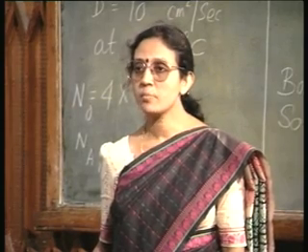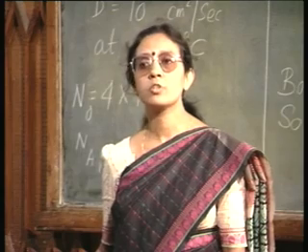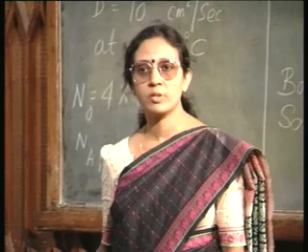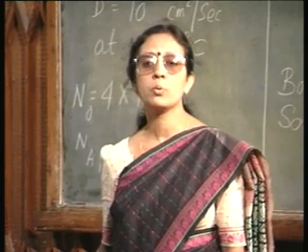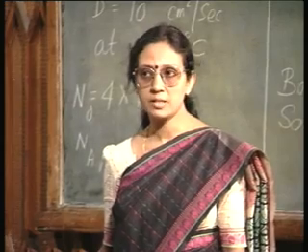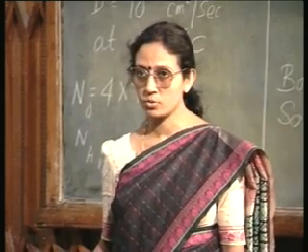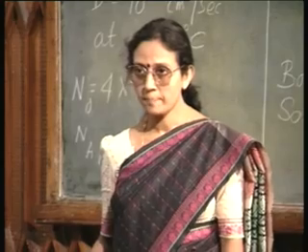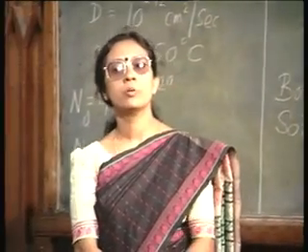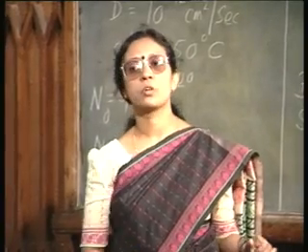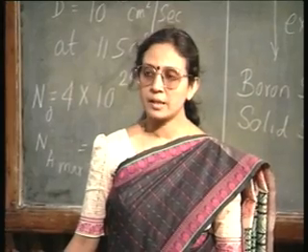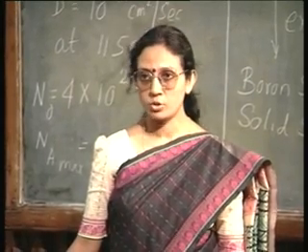Okay. So, you are controlling the formation of B2O3. You are just activating the boron nitride wafer prior to the diffusion, when only a thin region is converted into B2O3, and that is going to act as a solid source. Okay. So, this is one choice of source for boron, the solid source of boron nitride, a very popular choice, but there are other possibilities also.